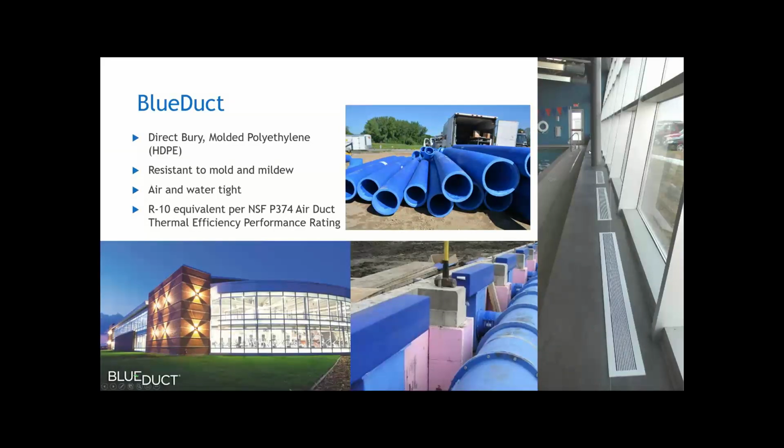Speaking of throwing against the wall, another great duct system that we have available is Blue Duct. This is a direct bury underfloor or underground duct made of high density polyethylene. It's very resistant to mold and mildew as it's air and water tight, and it's R10 equivalent per the NSF P374 air duct thermal efficiency standard. So you're providing yourself a duct system in the structure so that you can keep that duct system away from the ceiling, and it's a really good way to provide your supply air to where you need it.